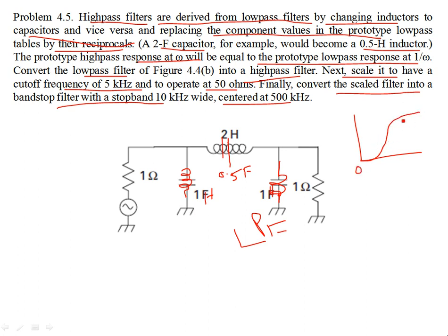The transmission will start occurring. You can consider any, for example, 3 dB point. This can serve as a passband edge. So this f naught is any passband edge having certain tolerance. It could be, for example, -2 decibels, -1 decibels, whatever it is. But this typical configuration is that of a 3-section high-pass filter.